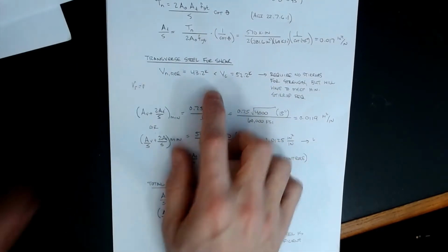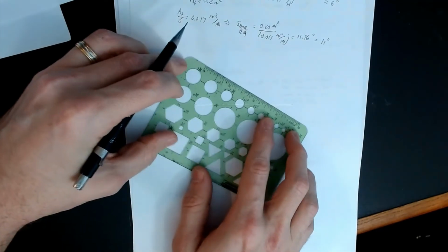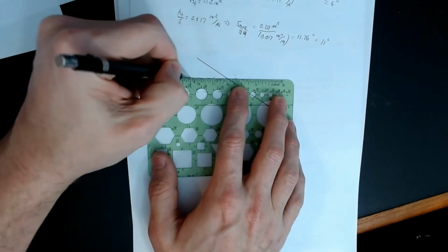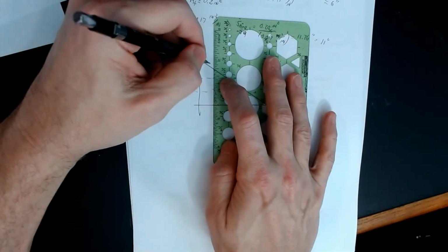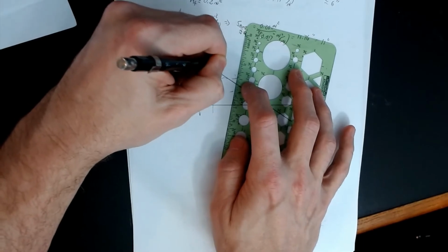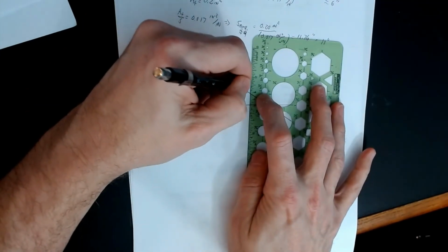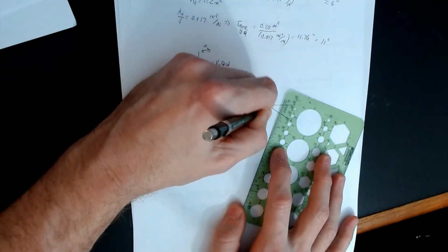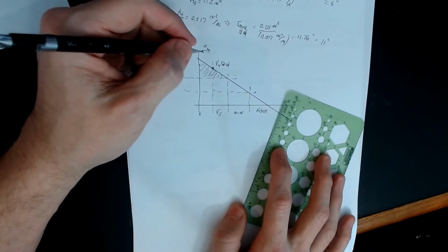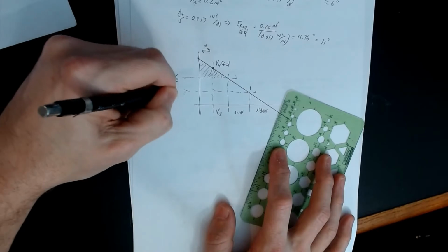But if you remember, that comes back to the diagram that we drew. It looks something kind of like this, that we had a series of lines. And this was my cross section. And again, this isn't exactly what my shear diagram looks like, but it's close. Here is my critical section, d. So that's my Vu at d. So this area would require stirrups, and then from here to here, this is minimum stirrups. This is none. And this is where I need Vs, extra steel provided to get the capacity. Remember that diagram that we drew? I hope. Do you remember what these two lines were? That one's Vc, and the one below it is Vc over 2.